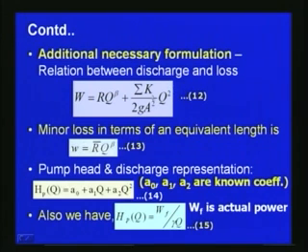So, here for minor loss we can say generally this beta is equal to 2. So, minor loss in terms of an equivalent length, as we discussed earlier, we can write W is equal to R bar q to the power beta. With respect to minor loss also we can add this, and then we can get a relationship between the discharge and losses, where R is the pipe resistance coefficient which we discussed earlier, and sigma k corresponds to the minor